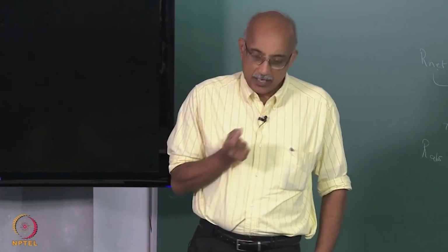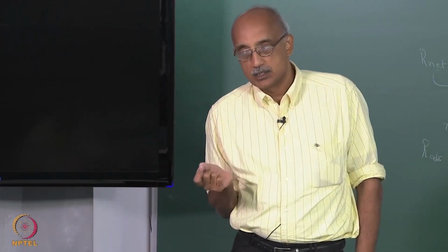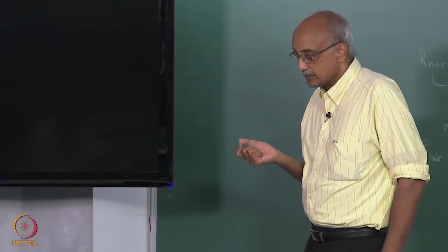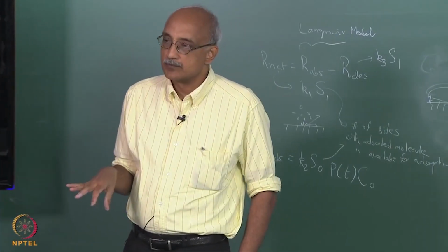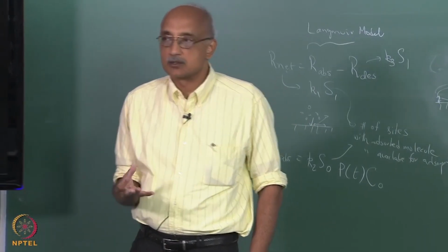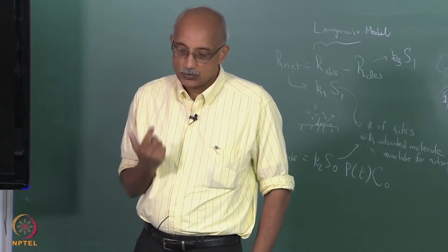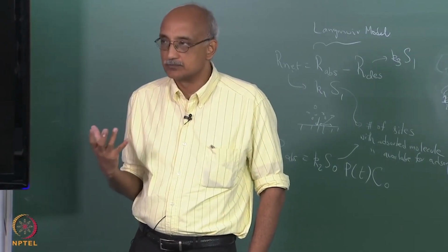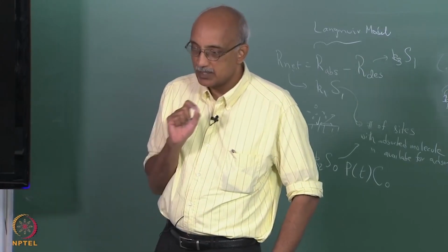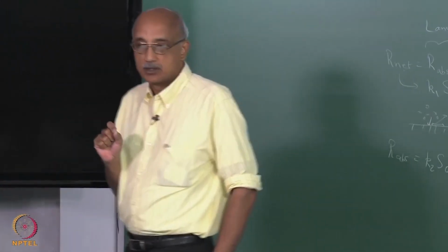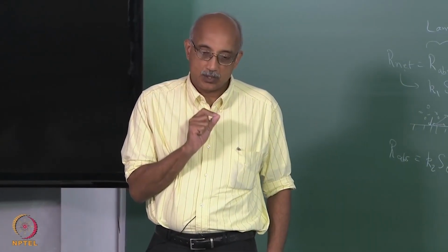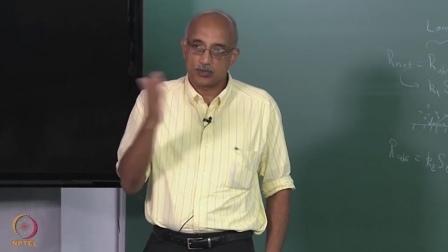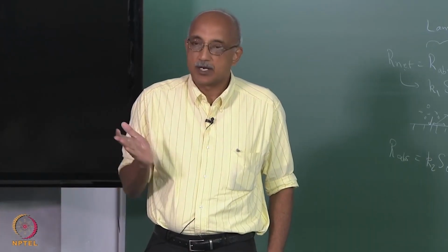Now, the challenge that presents is that when you have such small concentrations, the limiting factor for incorporating the dopant into your film becomes the thermodynamics of the system. You have to start with the thermodynamic phase diagram, because the amount of material that is going to be available to form the dopant in the film is going to be very, very small. And so, unless you are operating well within the thermodynamic constraints, the film may never form.